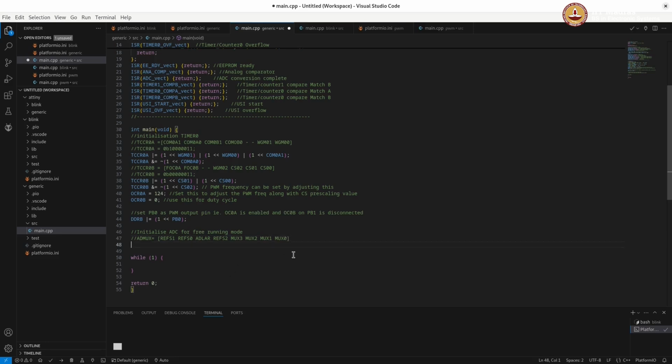So we had said that ADMUX can be equal to 0B01000011 if you want to choose channel 3.